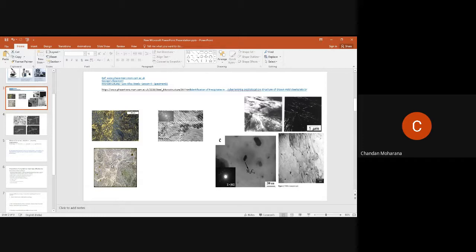Okay, what is the solution of this? Can anyone tell me the solution? We have to prevent the formation of the network of cementite, right? Because once the network of cementite forms, you cannot avoid a crack if it is formed along the grain boundaries, right?